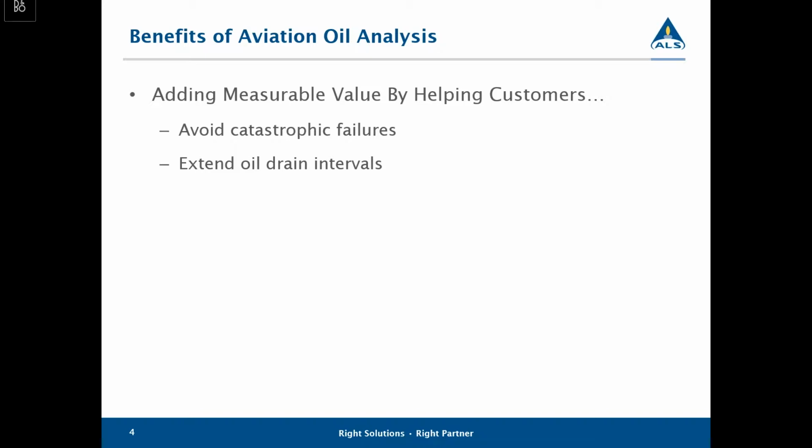But many pilots might be more proactive in their maintenance. They might fly more conservatively. Other things that might come into play is extended downtime, where that might actually have a negative effect on the oil by letting an aircraft sit for a very extended time. So doing regular oil analysis will help you understand what's a good oil drain interval for you. There's a possibility that it needs to be shorter, and there's a possibility you can extend that. It's something that you can gain both on the aviation side as well as on the ground side of things with ground equipment.